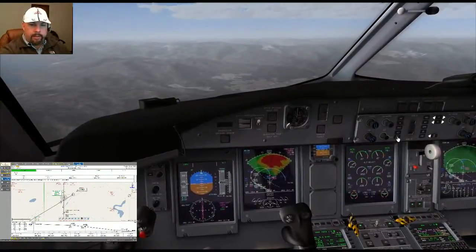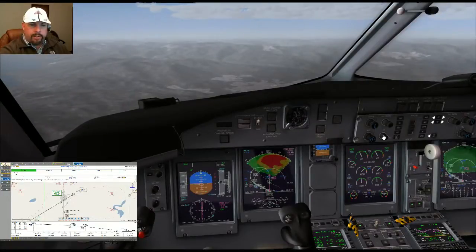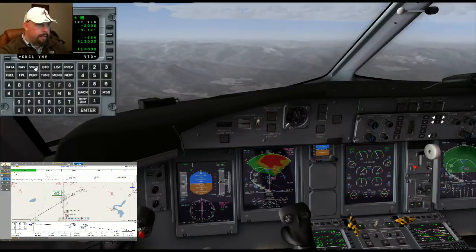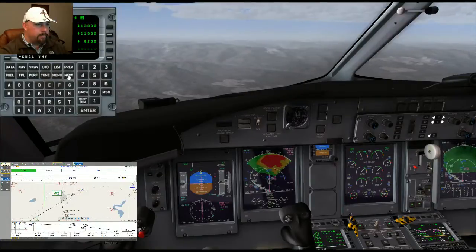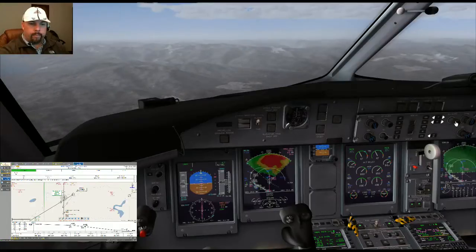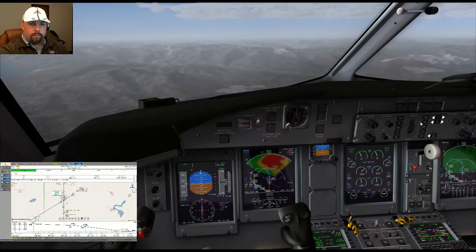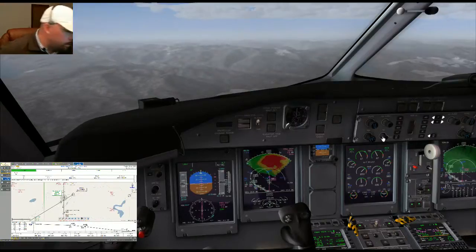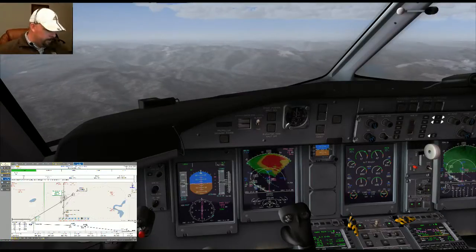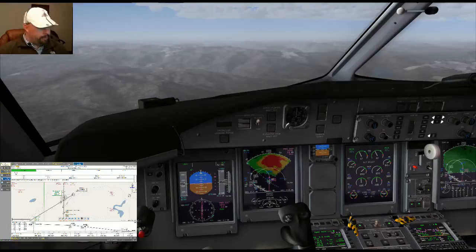We are inside at 2 minutes here. We are set up the LNAV and the VNAV, and let's get an idea here. After 13,000 feet at Tipio, our next altitude will be 11,000 feet. Set 11,000 feet. And then after that, we'll be on our way down to 8,100 feet. Again, at least for a while here, I'll try to keep the speed up around 230.